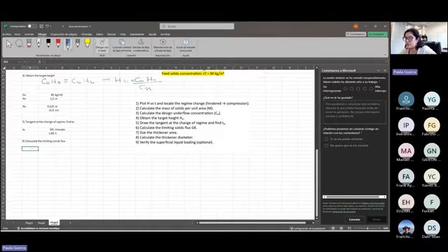So the limiting solids flux, I mentioned it before as sort of the equivalent to the surface loading rates. It's going to be calculated as the mass of solids over area divided by TU. Or in other words, this is H0 times C0 over TU.